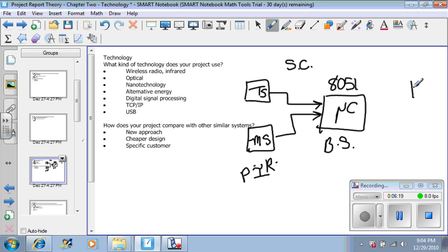On this side, for my lamps, I have many techniques to operate my lamp. I could try and connect the lamp to the microcontroller, but that's not possible because the microcontroller does not have enough current. So I need to find another way to give current to this lamp.